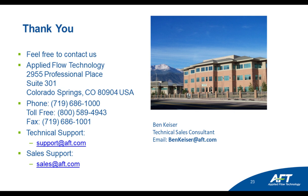One example is piping component files that come from isometric drawings from various CAD software, or neutral files from pipe stress software. You've already taken the effort to build your piping system in other software tools to do different things, and if there was a way that you could bring that into a flow analysis tool, you would want to be able to do that to save you time rather than having to build it all again from scratch.